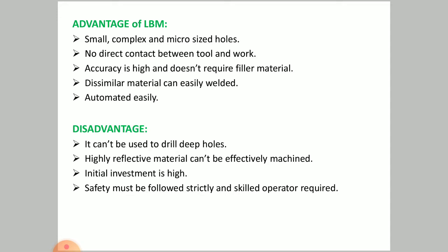Now let us see the disadvantages, the lacunae of this process. It can't be used to drill deep holes. Why? Because the concentration will get lost with the depth, and that is why it is not much effective in the depth portion.